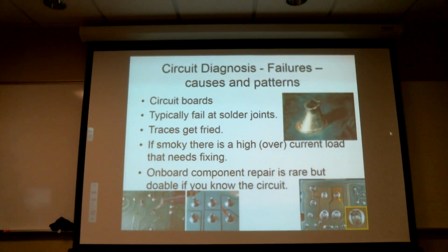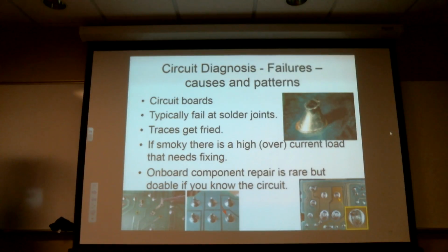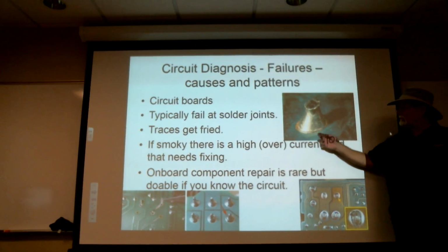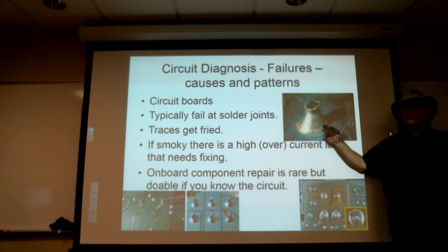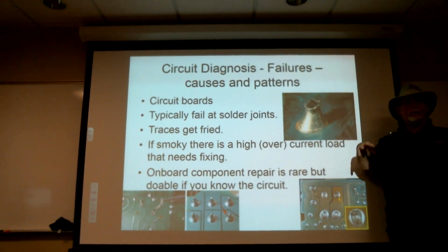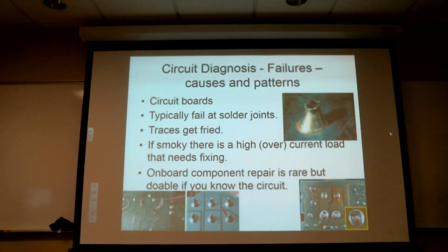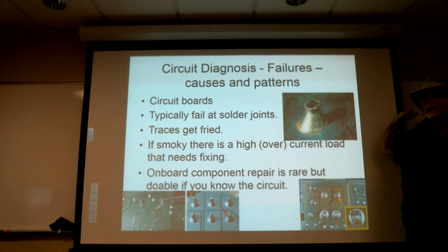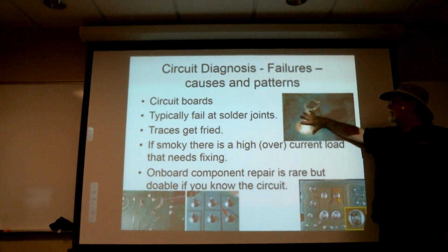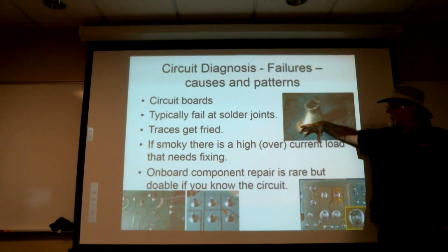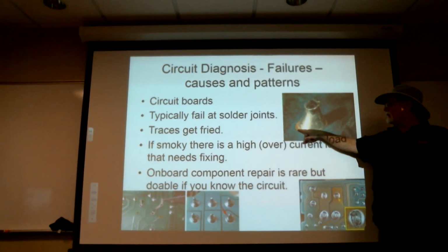Circuit boards. I've made a lot of money off these babies. So the more common failure when they do fail is that a little San Andreas fault forms its way around here. What happened is you have a fairly big lead that went up through there. When this went through the wave soldering process, they weren't preheating well enough, so this lug that's sticking up wasn't hot enough. And so when it went through the wave solder very briefly, the solder flowed into here, but this sucked so much heat out of it that this solidified, but this was still jellied, and it shrunk up just a little bit. So it created a bunch of little microfractures.